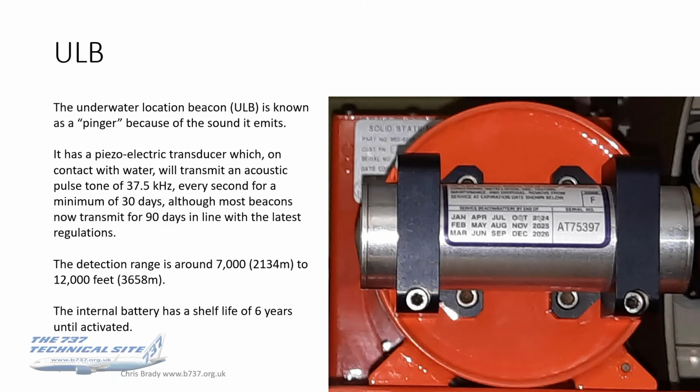And the internal battery has a shelf life of 6 years. Now that's not to say the thing will transmit for 6 years. It won't. It'll only transmit, as we know, for 30 to 90 days. This is the shelf life of the battery until it's activated. So it's an engineering check. I think they do a serviceability check of the battery every 3 years, and then they replace it every 6 years.